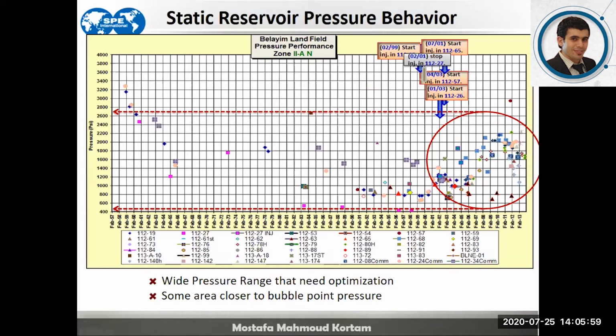It would have a great pressure gradient and pressure contrast between the producer wells that are opposite to the injection and the wells that are far on the crestal side, far from the injection line. So the reservoir pressure itself requires some improvement in order to raise the production, since the pressure at the producer wells far from the injection is low.